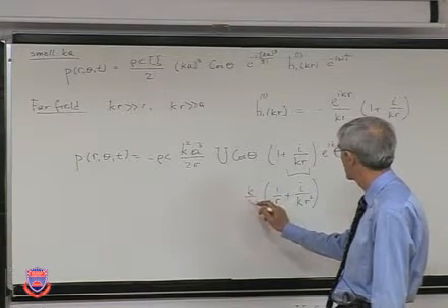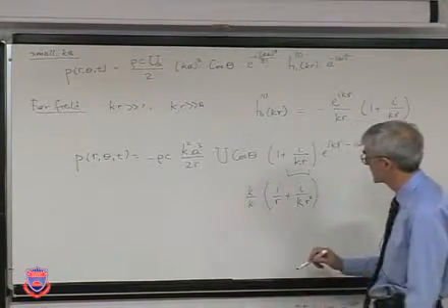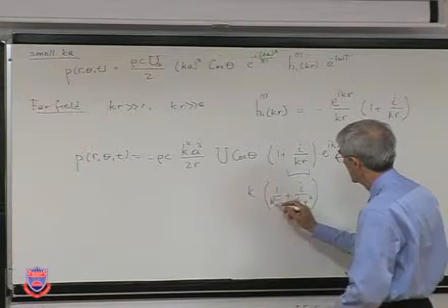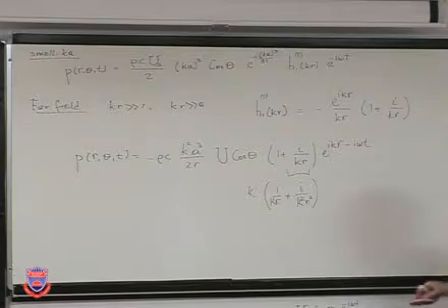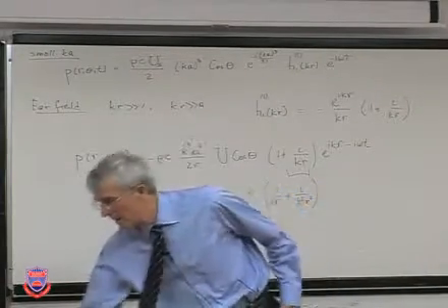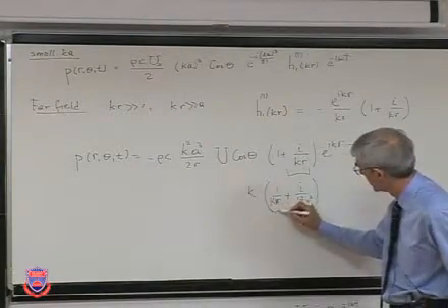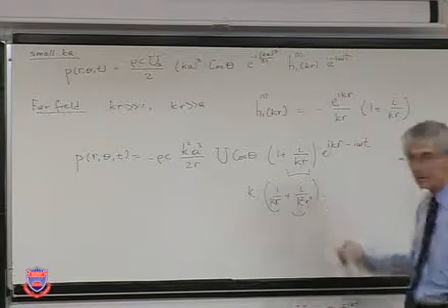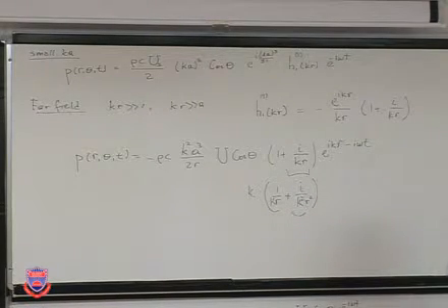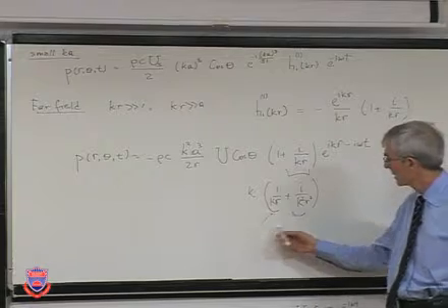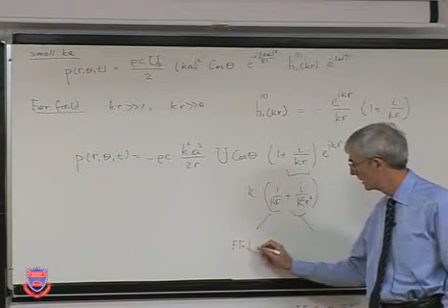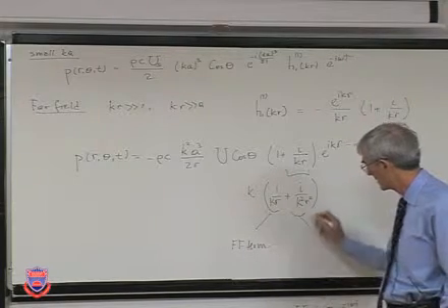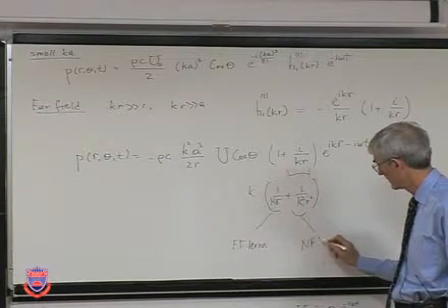If I just briefly do this, okay. When you look at this, you see this 1 over Kr and 1 over K squared R squared. What we commonly refer to these as is a far field term, and this is a near field term.